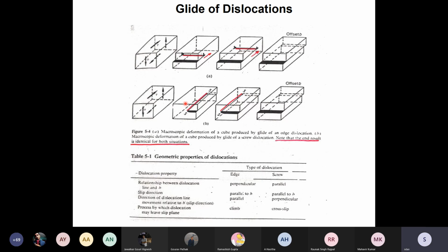So you got a plastic or permanent deformation of that wooden plank, even though you did not load it significantly. At the beginning the plank was horizontal, but with time it bent. And this phenomenon is called creep, C-R-E-E-P. Even though loading is below the elastic limit, with time deformation takes place.